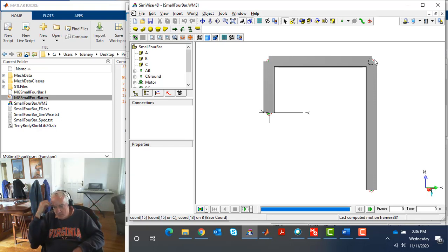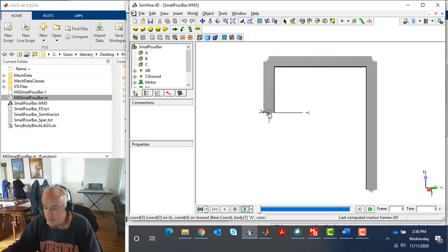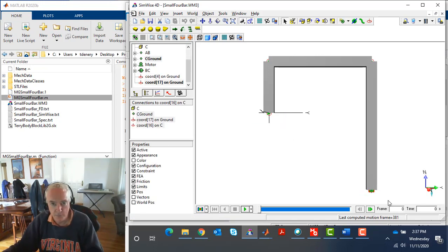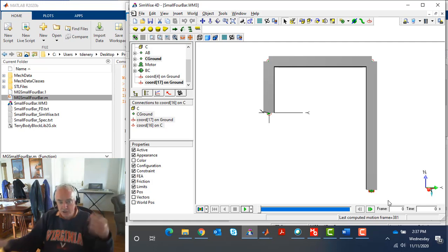But where there are 4 joints, that might imply 4 degrees of freedom, because there is a physical constraint, where the linkage ultimately connects back onto itself, because both the motor right there and this final connection both connect to that same ground, that there essentially is a loop. And that loop constraint itself will reduce these 4 degrees of freedom down to 1.